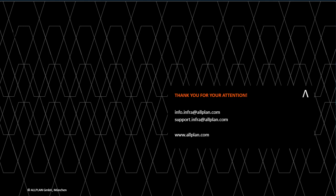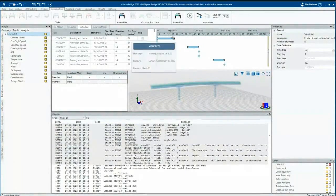Yes. So regarding creep and shrinkage calculation, we calculate creep and shrinkage from the time point where our elements are activated all the way up to the next time point where our statical system changes by the activation of further elements in our system.